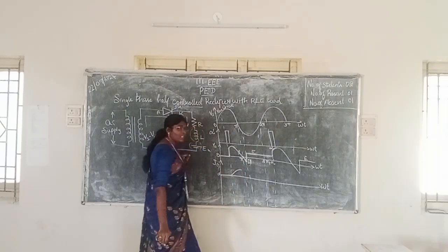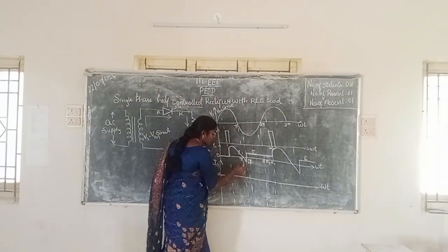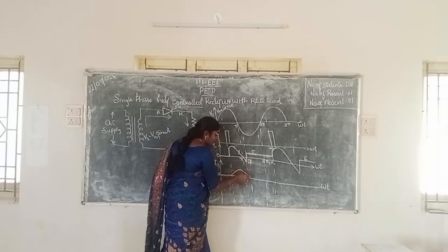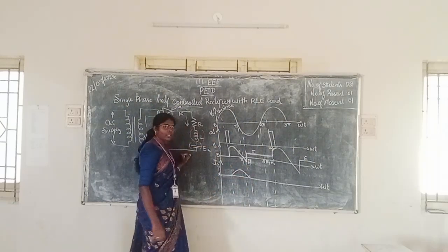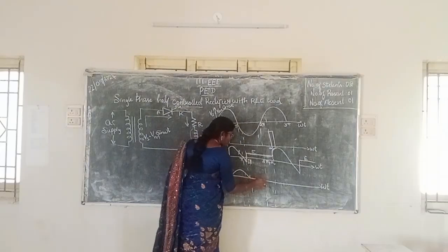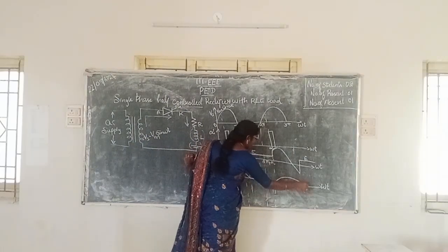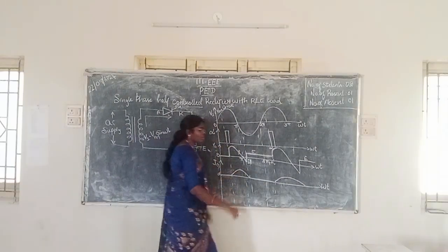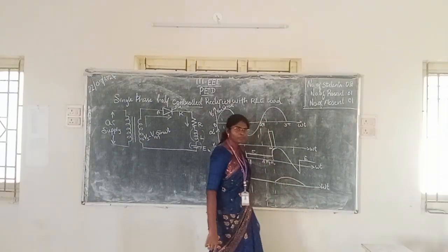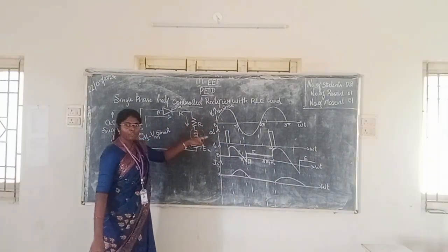After reaching a maximum point, it will reach 0 at the beta point. After that, it will remain 0. During the next half cycle, it is going to increase, and then at the beta point, it will decrease. So this is the output current with respect to omega t. That is all about the RL load waveform.